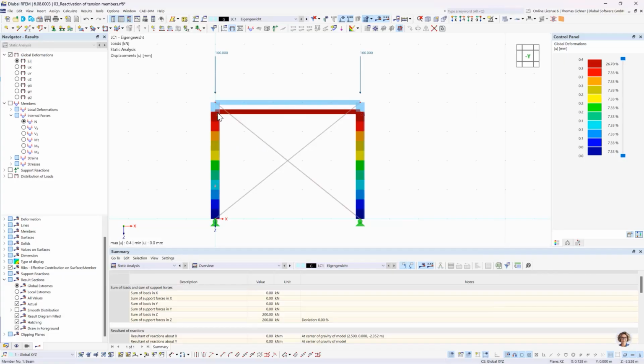And now we see what happens here. We have the system, it's just gonna deform in vertical direction. That means these tension cables would shorten. That means they would need to take pressure, and that means they are gray now since they both failed.